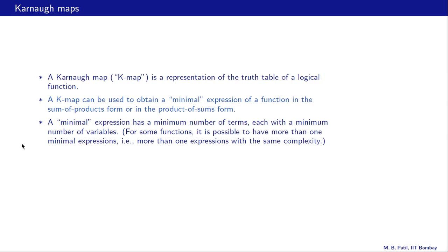The answer to that is mostly yes, but for some functions it is possible to have more than one minimal expression. Alright. Now why are we interested at all in minimal expressions? This is the reason. A minimal expression can be implemented with fewer gates, and that's why the implementation is cheaper.